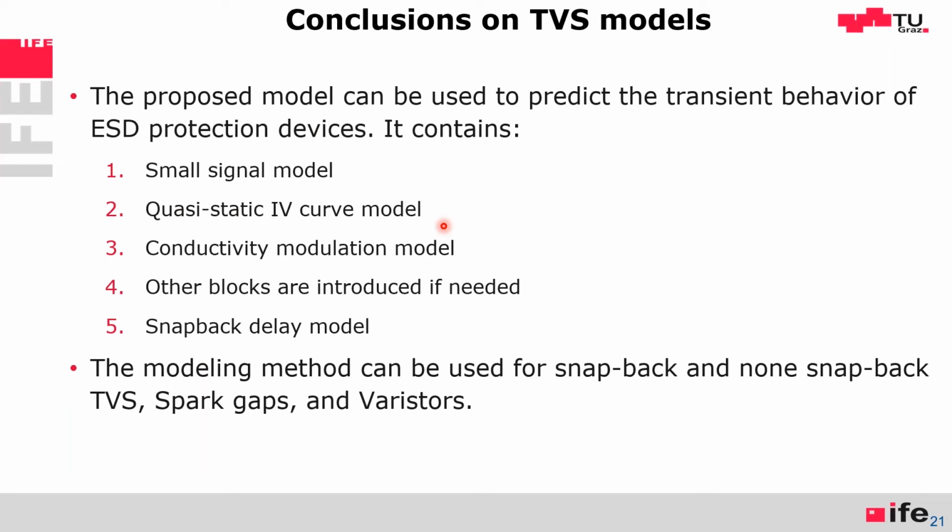The TVS models, the ones done here, have a small signal model. They model the quasi-static curve, and then all the turn-on effects, which are snapback delay, conductivity modulation, etc. They're all modeled in the SPICE model, and the modeling frame can be used for snapback, deep snapback, varistor, spark gap. The parameters, of course, need to be adapted based on the measurements.